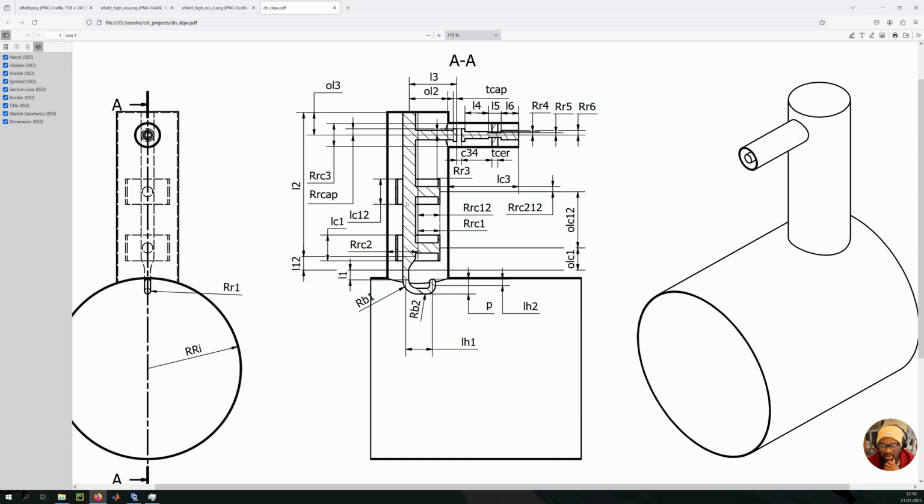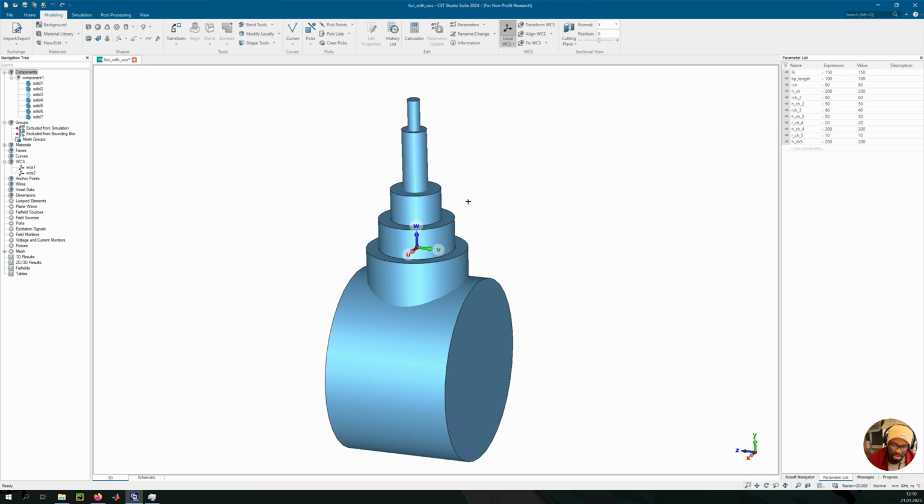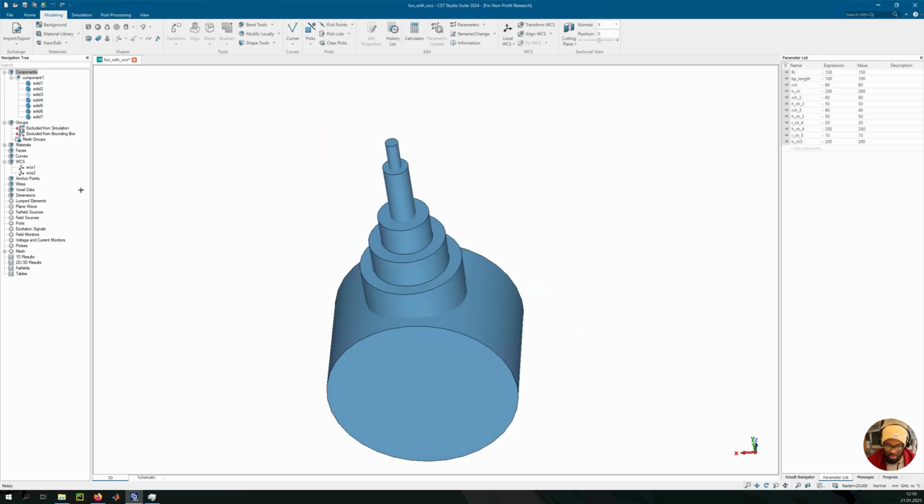It could also be the case, but then getting the first dimension I still have to calculate. For me it's easier because I already calculate the whole length, and then I just copy and paste, and delete some of the dimensions from this entire length which I have already calculated. So I think that's why it was natural to me. You may have a different model, and then this might be more effective. And if you want to go back to the world coordinate system, you just click this and you can return to any of the coordinate systems later.